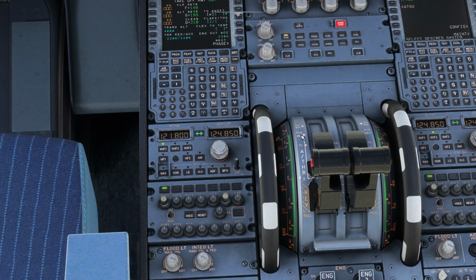Now, flex temp is a methodology used by the airlines to have less impact and stress on the engines. There is a formula to calculate the flex temp, but thanks to the takeoff performance, it comes over here. You can take the flex temp. What it does is it gives you a temperature higher than the outside temperature. So let's say if it's right now 40 degrees centigrade in Lahore, the flex temp might be 46, 50 or 60 depending upon the calculation and all the factors.